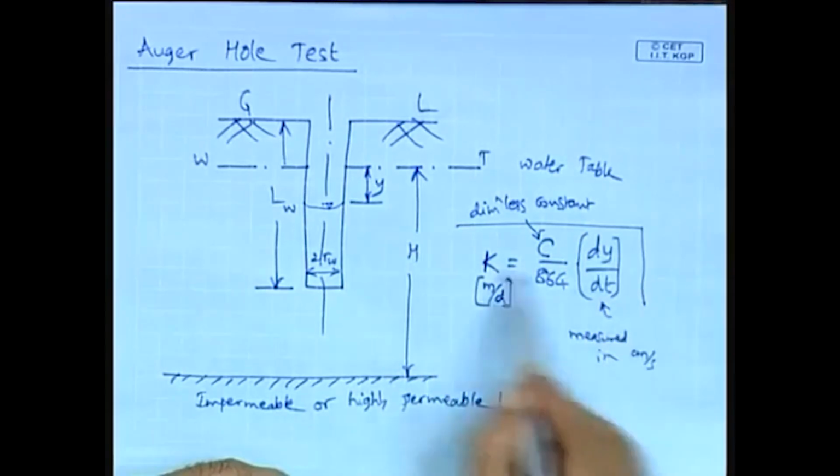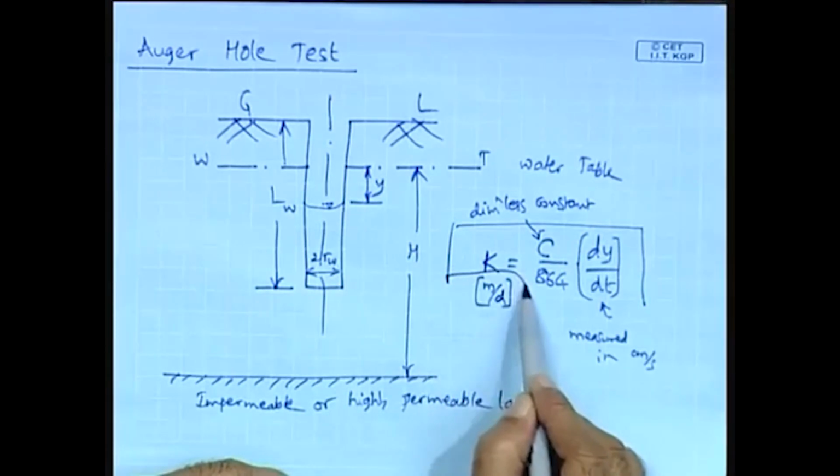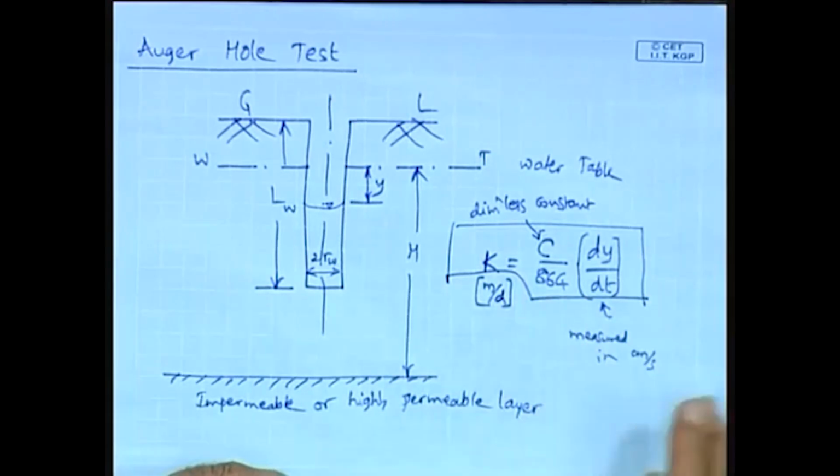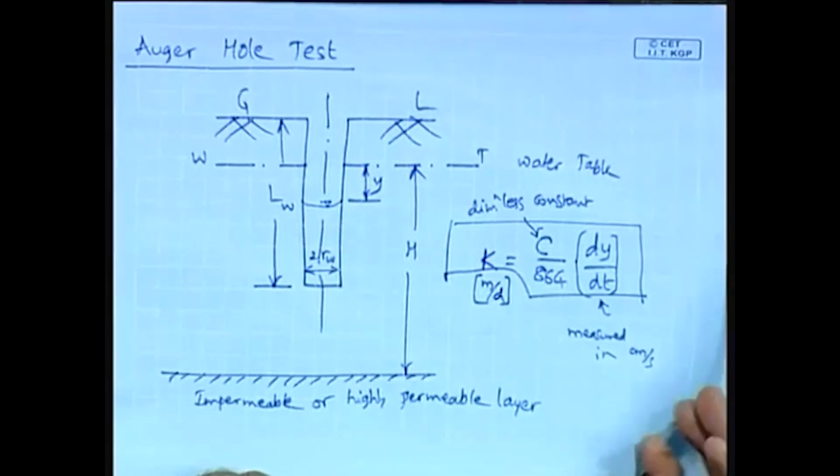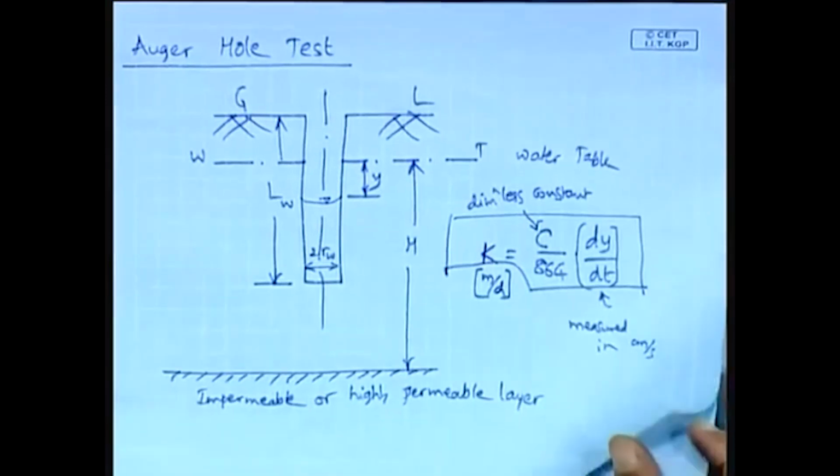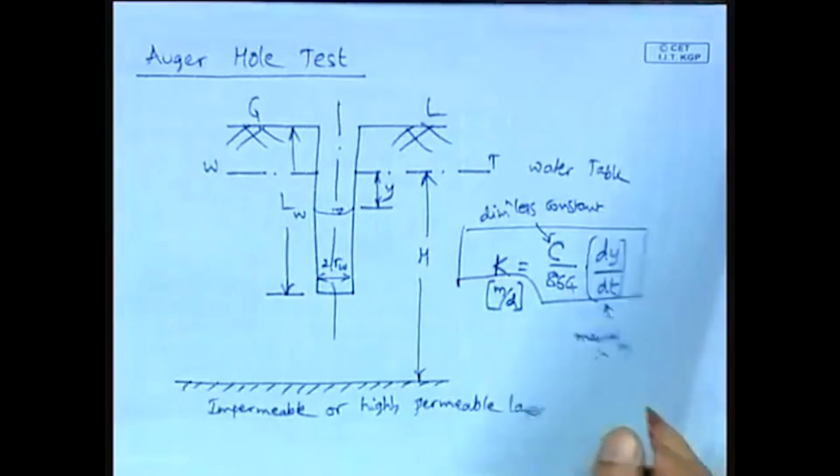So, this is the expression for the hydraulic conductivity through this auger hole test. Now, let us come to the last one. Anyway, of course, we will go into this, that is the pumping test.